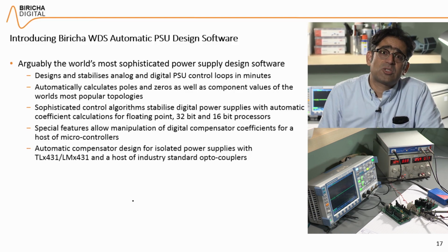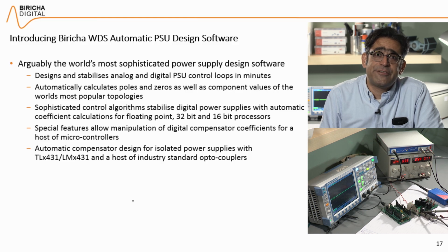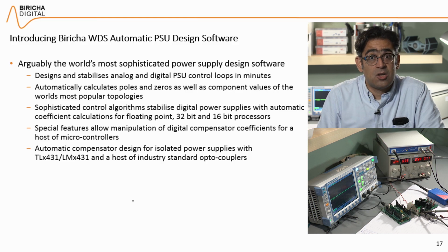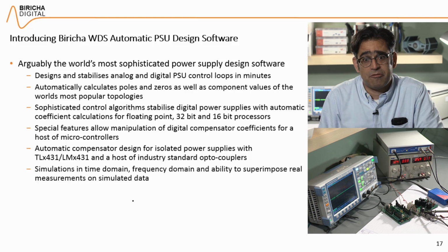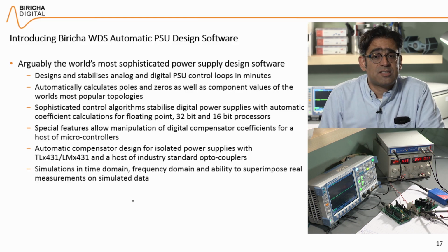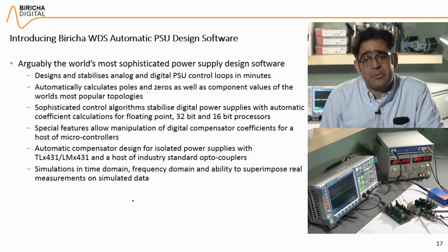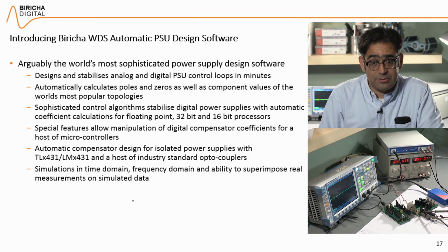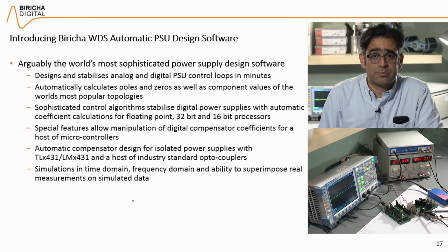And for analog power supplies, it also designs with TL431 and LM431 with the optocouplers, which you can characterize, and we teach that in our analog power supply design workshop for isolation. And then you can have simulation in time domain, in frequency domain, and the ability to superimpose the real measurement on the simulated data. I will do that shortly in a demo.